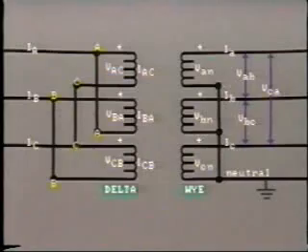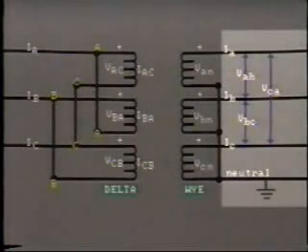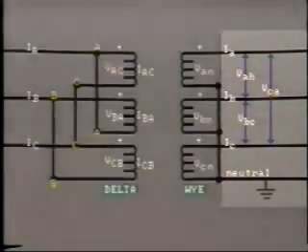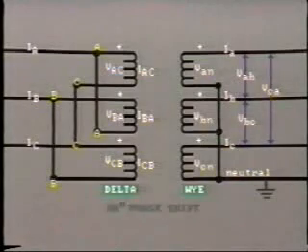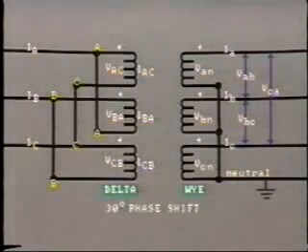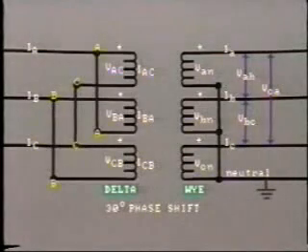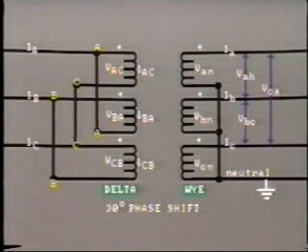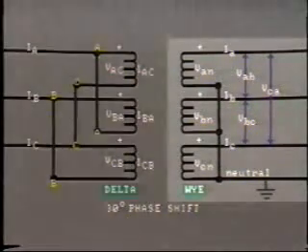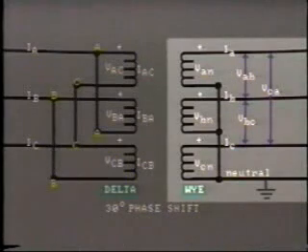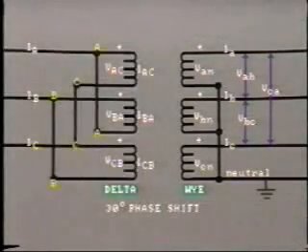This delta-Y transformer is feeding a three-phase, four-wire distribution line. A delta-Y transformer has a 30-degree shift in voltages and currents between primary and secondary. In fact, as this example will show, the polarity markings and connections shown here have the primary leading the secondary. The neutral is grounded. First, phase relationships on the Y-connected low-voltage side.